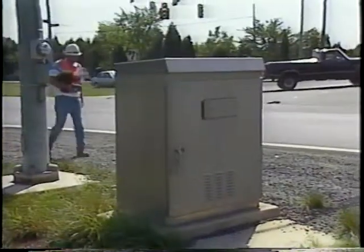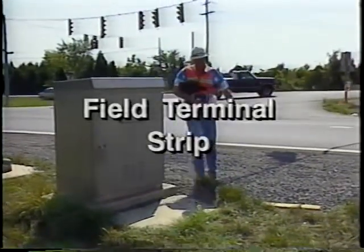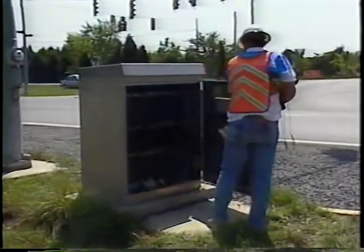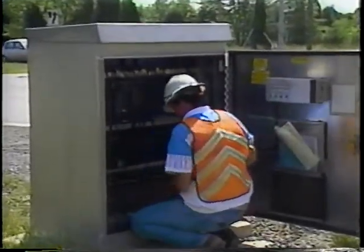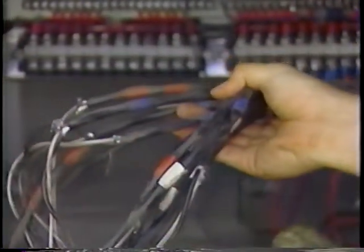The lead-in cable will end inside the controller cabinet at the field terminal strip. Most manufacturers recommend grounding the cable at the cabinet. This entails connecting the shield to the terminal and insulating the end of the cable in the pull box. This allows any electrical disturbance or interference to be safely grounded without affecting the loop lead-in cable.